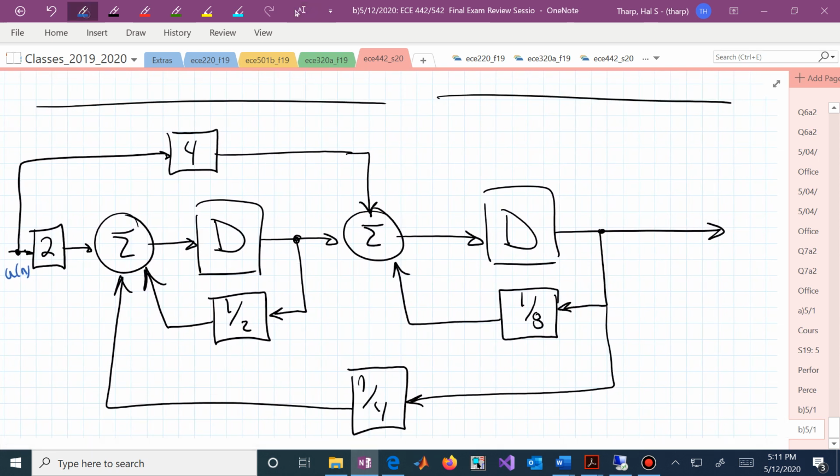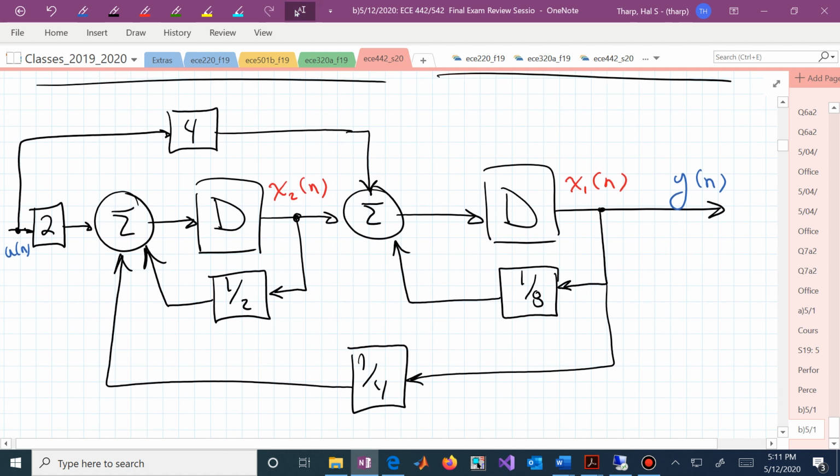Moving on, let's now talk about block diagrams and how we go back and forth, how we dance in this four-square representation of these different ways of describing systems. We can now say, here's our output y of n, there's our input u of n. If somebody now wanted a state space representation, you would immediately say, what I need to do is define my state variables as outputs of these delay blocks, and then I'm good to go.